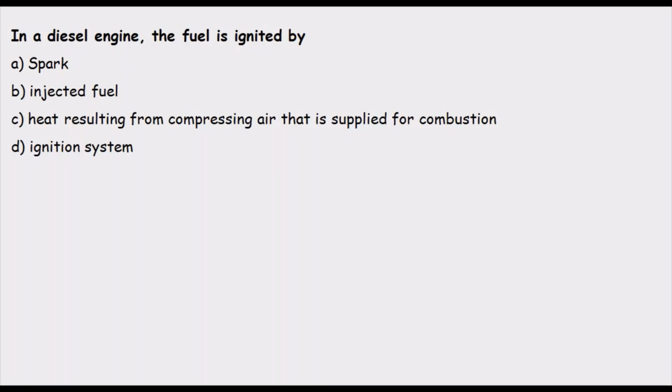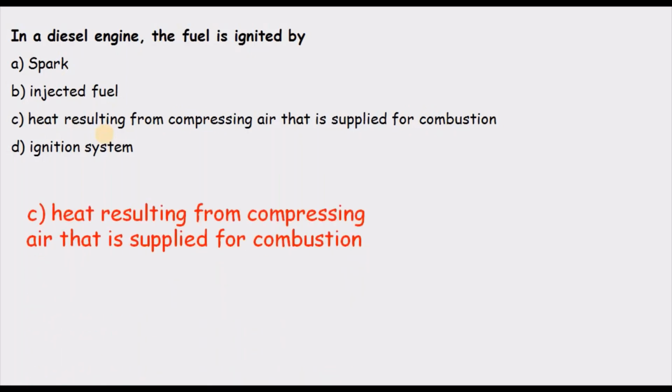So the correct answer here is not the spark. A spark is not used. An ignition system is therefore not there. And injected fuel, fuel being ignited by injected fuel is not possible. Therefore the correct answer is C, heat resulting from compressing air that is supplied for combustion.